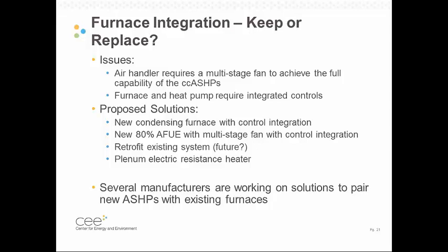Another option that we considered was to get the really nice multi-stage fan and controls, but to install a cheaper furnace. So to go with an 80% furnace that's still new, so it still has some cost, but is a little bit cheaper. And we thought that might be okay because we're really trying to limit the amount of runtime on the furnace anyways. So if it's only covering 10-20% of the heating load, maybe the impact from going with the 80% furnace is worth it.